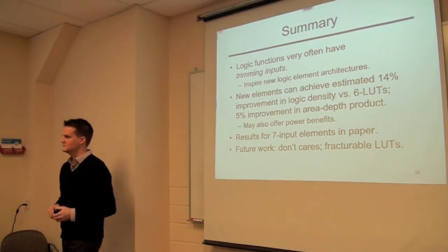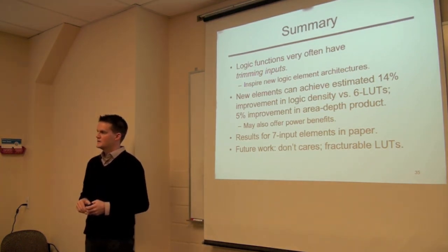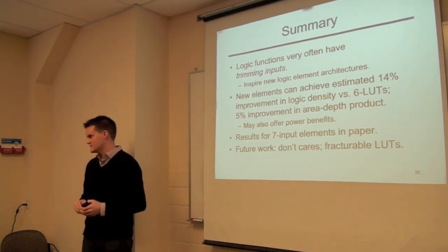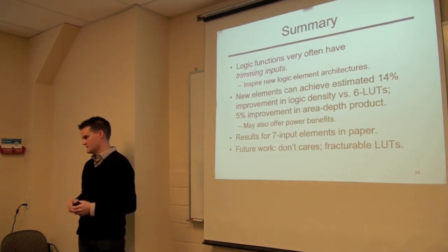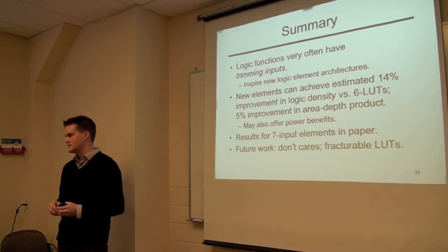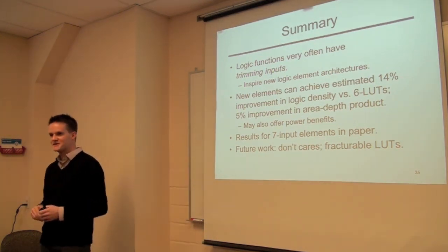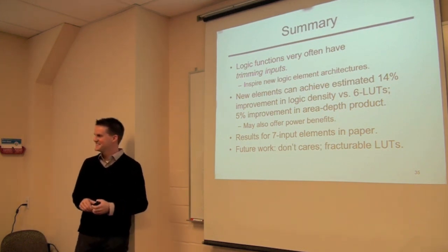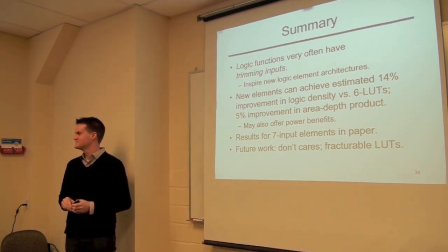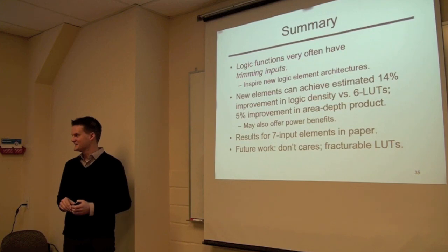These are the multiplexers inside the LUTs, but not the multiplexers inside the block itself that are doing the internal routing. No, and we assumed that was in the 50% of the tile. That 50% of the tile was routing, so that part is a constant. We're only attacking the 25%. If any industrial people want to say what fraction of a tile is LUTs, we're happy to hear it. I don't know off the top of my head, but the 25% doesn't strike me as out of line. I think that's probably close to what my guess would be as well.